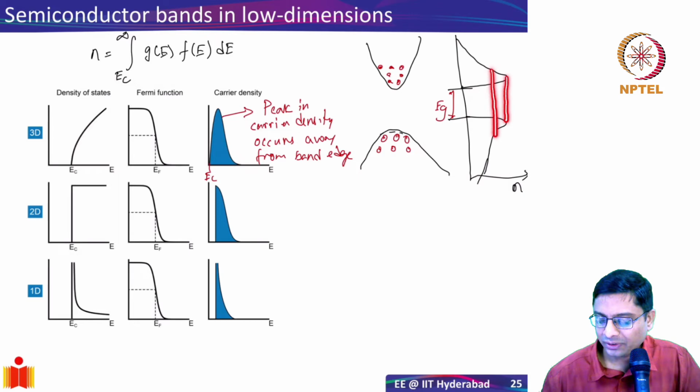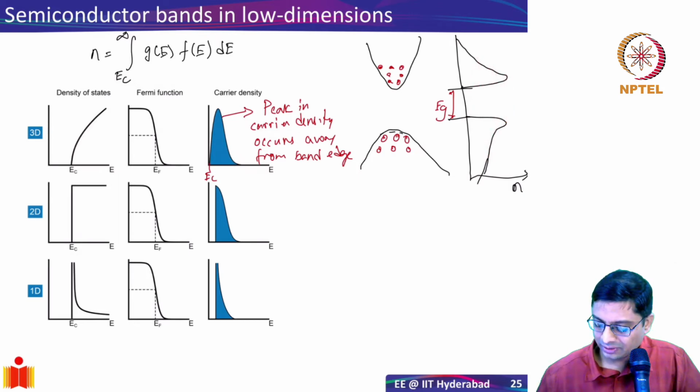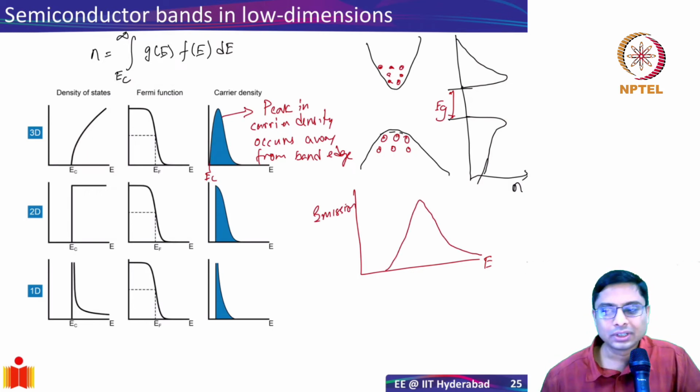After that, again, the number of electrons and holes is lesser, and the emission reduces. So if I talk of the spectrum, energy versus emission, something like a photoluminescence spectrum, you'll see some broadening like this. The reason is the peak is not at the edge. All right. Is that clear? Are there any questions? Clear?